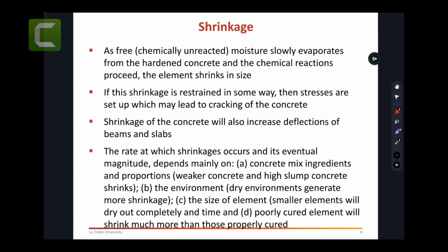If you're going to have a concrete slab within an internal environment, so it's not a wall or a car park, then that means it's internal. Then you have to design for moderate or internal environments. And basically, you will end up using a one line, a very small relationship, to give you the correct crack control figures, full stop.